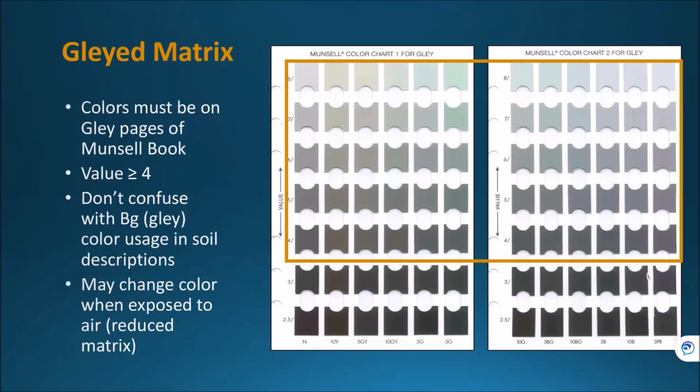I like to say that soils are a good historical indicator of what the pre-existing conditions were before we started manipulating and draining and things like that, because once these colors appear, they don't necessarily go away that easily. So if you're seeing these types of colors, then historically, from a development perspective, they've probably been pretty wet in the past. That means you've probably got a really good chance of restoring or enhancing that back to its natural condition. So next slide, please.